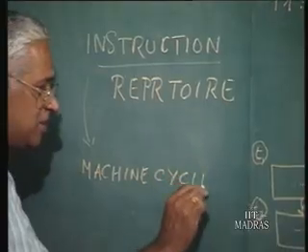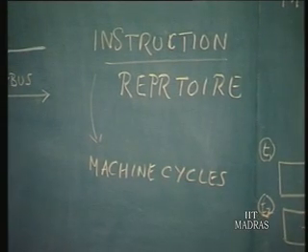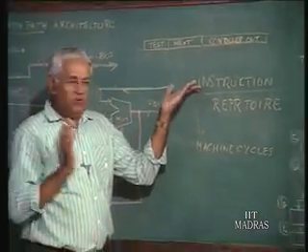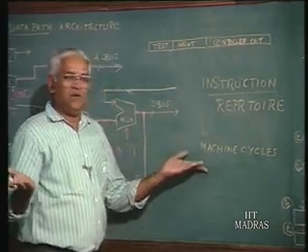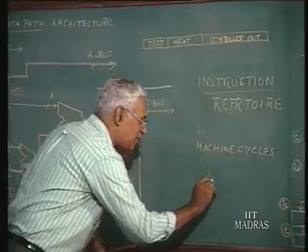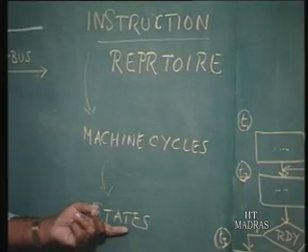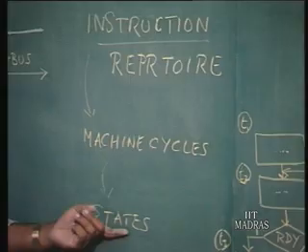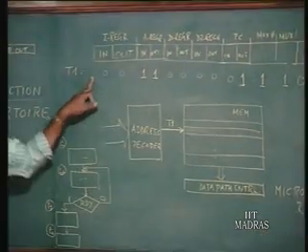It all depends upon the type of the instruction, the width of the instruction. As I was already mentioning, if an instruction word is 3 bytes, for fetching the instruction itself you need 3 machine cycles, and then you have the execution part also, and then each machine cycle consists of specific states, and in one state one low level activity, a register transfer level activity takes place, and what we have here is for one such activity for which the data path will be set up.